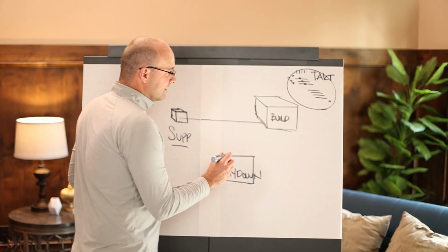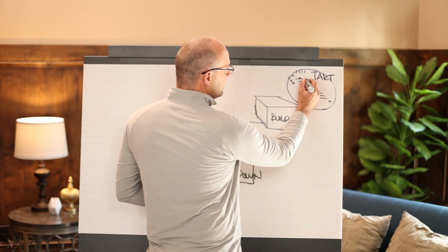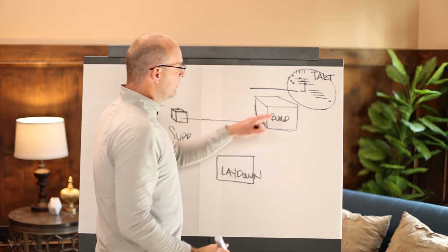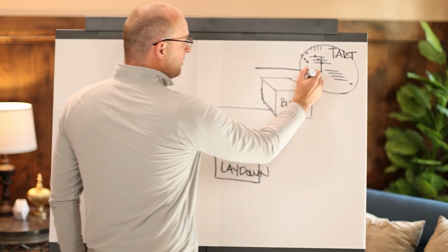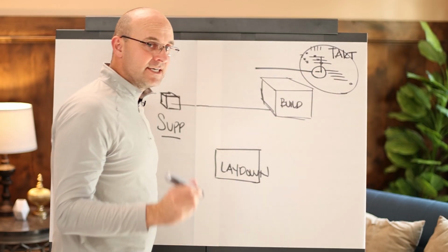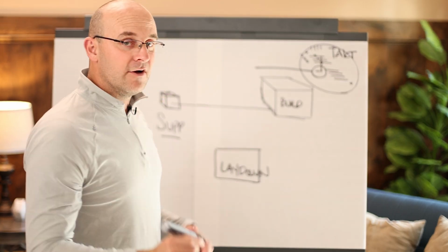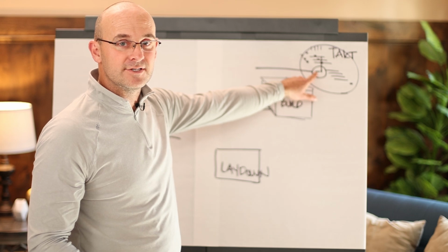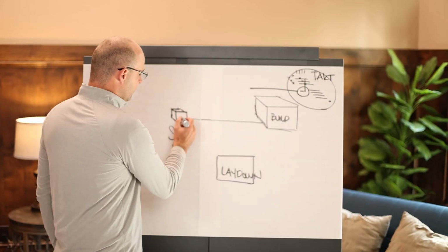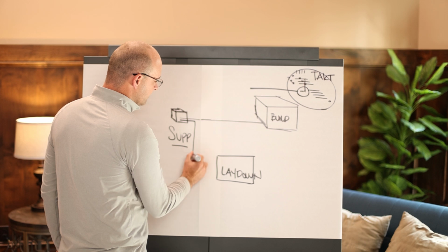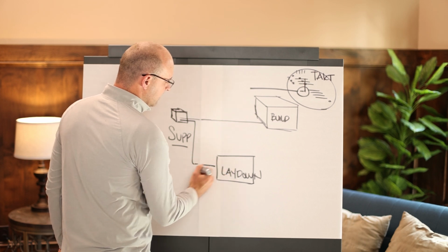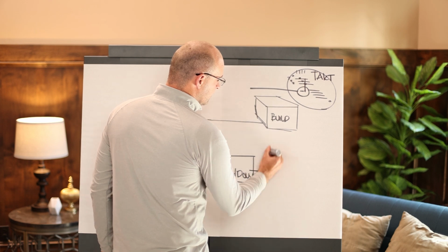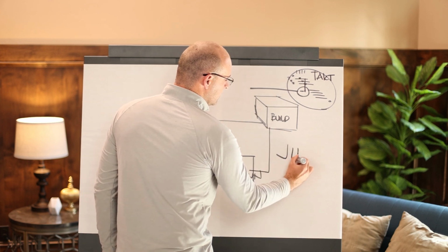But if you can't, and you'll remember that if you have an activity, you need a buffer and you need to account for that supply chain. That means that you have a material inventory buffer of materials that you want a certain amount of time before that activity starts. That means that you will order the materials from the supplier and you will stage them at the laydown yard and only bring the materials to the place of work just in time.